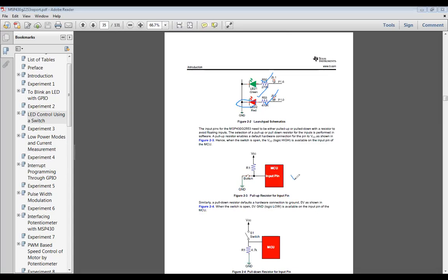When you connect a button outside your breadboard, you can also pull it up. You can also pull it down, tying the other plate of the button to VCC. This is a valid setting which we could do. Hope you can understand.